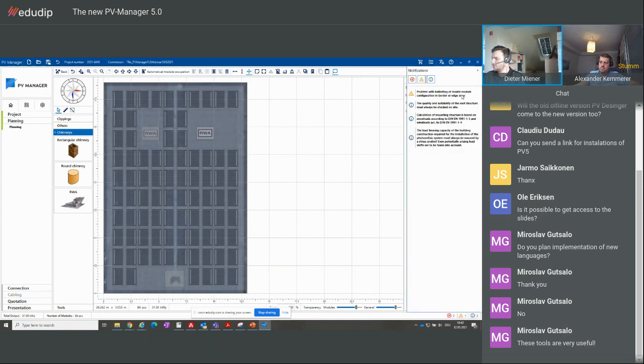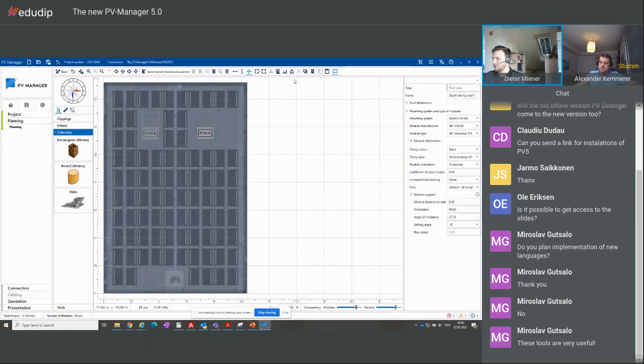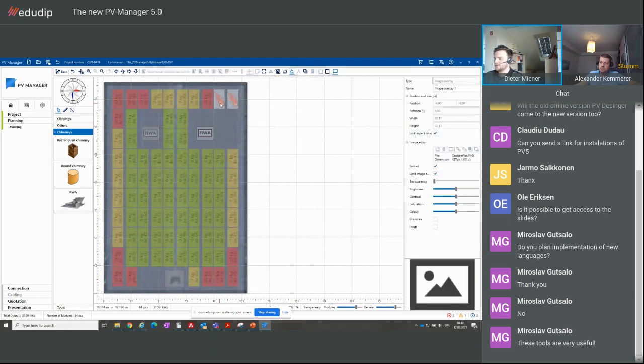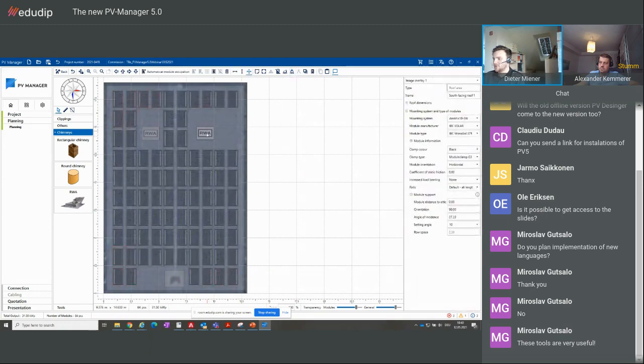Problem with ballasting of invalid modules. Okay, so we have a ballasting problem. The ballast can be checked here. The issue is that these modules are not able to be ballasted, and if you see some lightnings, then either delete the modules or try to change the setup.